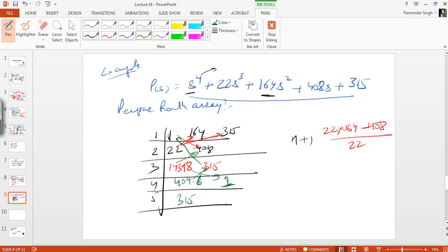Now the important thing about the Routh test. Now look at the entries, now the row is completed. Number 1, remember this thing. First we need to finish up the row. Now row is finished. Number 2. Now once the row is finished, take a look at the signs of all the entries which are there in the first column.